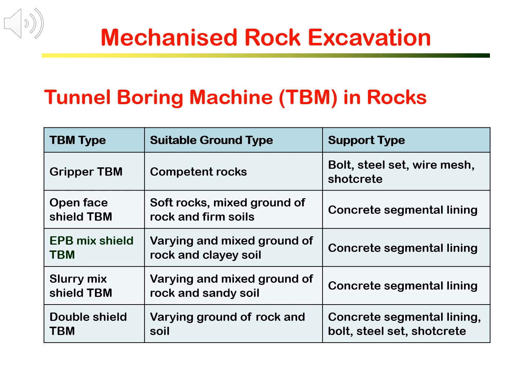They are primarily developed for tunneling in soils. Therefore, when tunneling in mixed ground of rock with soils, shield TBMs are used to protect the ground from collapse. The TBM cut head is mounted with roller cutters for rock excavation. They can excavate both rocks and soils, and at the same time give protection to the unstable mixed ground.